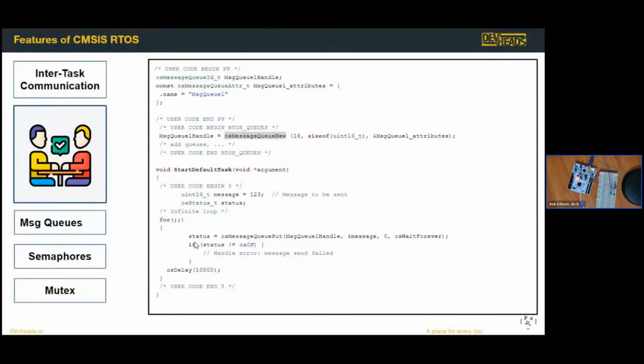So inside this task, we have the forever running loop. So this is similar to a while loop. That means that task will never stop running until maybe you delete the task, or you can suspend the task for some minutes to make it stop running.